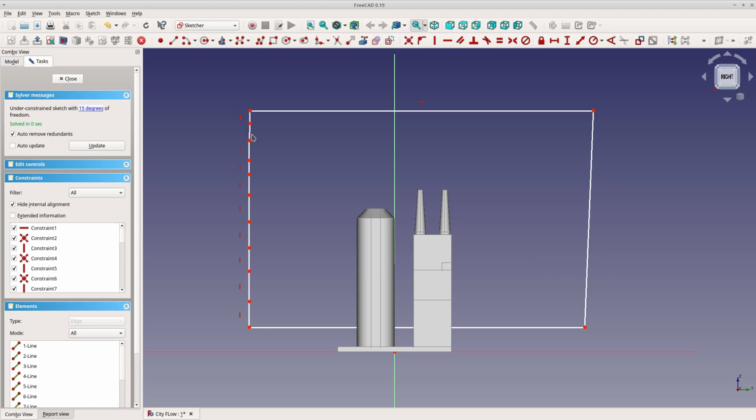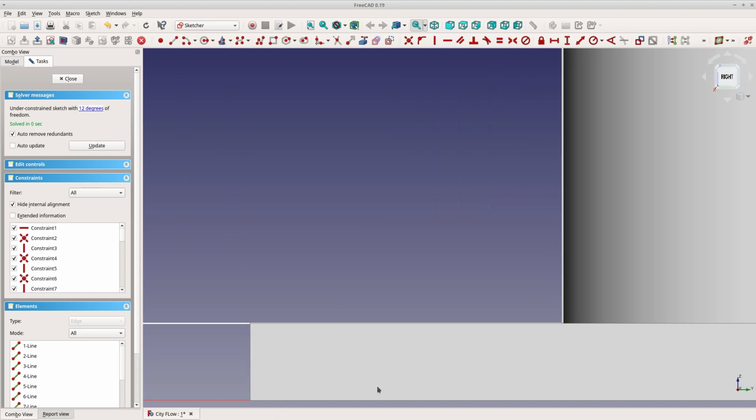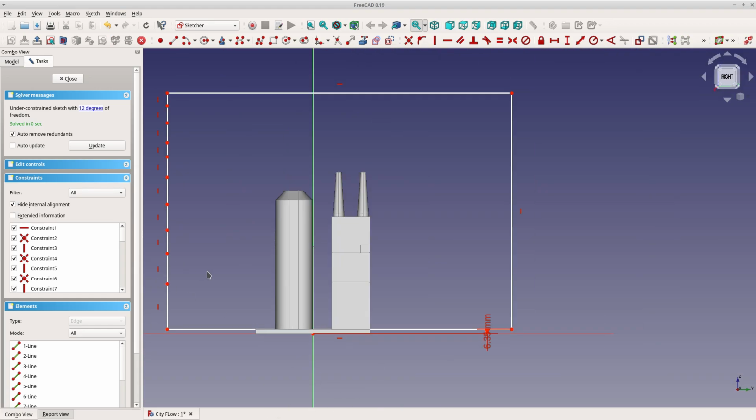All right, I'll use the V key to make this one that is off vertical into a vertical, and V here as well. I have this already horizontal, so we're good there. Let's grab our origin and this outer point and say Shift V to add a vertical dimension. Let's say something like 6.35, I think, and that puts the line right at ground level.